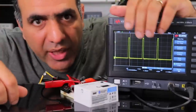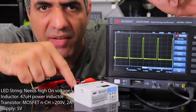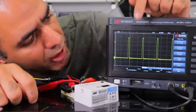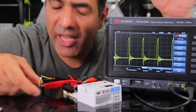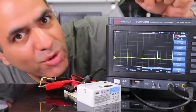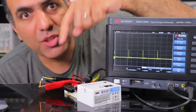Here I threw the circuit together with whatever components I had. The LEDs are here, a 47 microhenry inductor, transistor, my 5 volt supply, and a 20 kilohertz PWM at low duty cycle. And if I turn on the supply, the LEDs don't turn on, but there is some noise. Looking at the output though, I see every time I turn the transistor off, I have spikes of 100 volts, which is apparently not enough to turn on the LED.